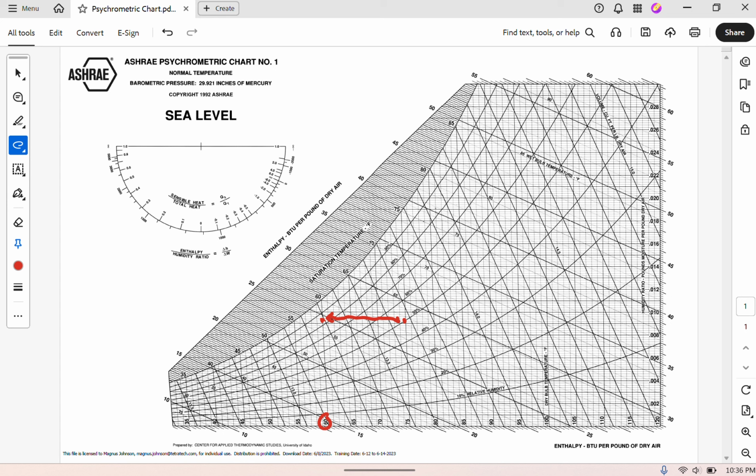You can now see why in a lot of cooling processes you actually see both sensible and latent cooling, because as you get closer and closer to that saturation line, you're going to have to start pulling moisture out of the air, because the coil temperature is likely going to be colder than your leaving air temperature, or it will have to be colder. If your coil temperature is, let's say, 55 or 50 in this case, you would see some condensation on the coil, and we would therefore see latent cooling even before we hit the saturation curve.